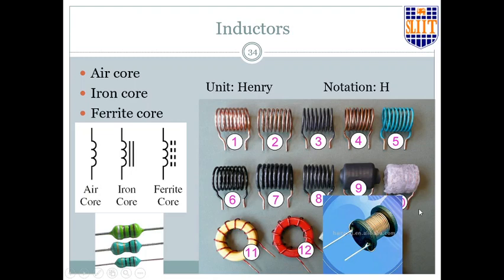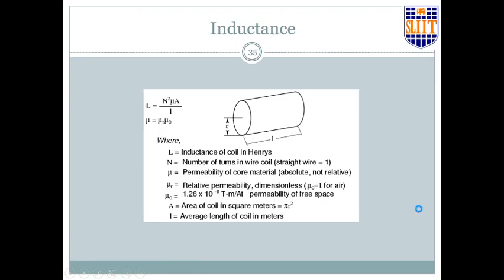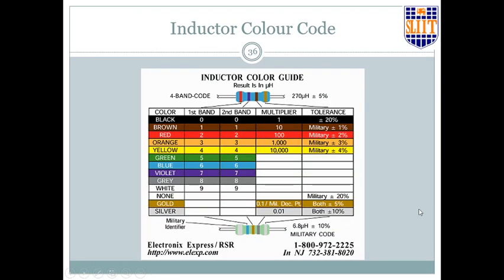Right? But this is very small, so you will get very small inductors from those. If you want a large inductor, you will have to buy it. Right? Millihenries, of course, you will have to buy. They are bulky. The large bulky inductors are in the millihenries range. Right? A similar color code is there. Same way you read it, 3 color bands.